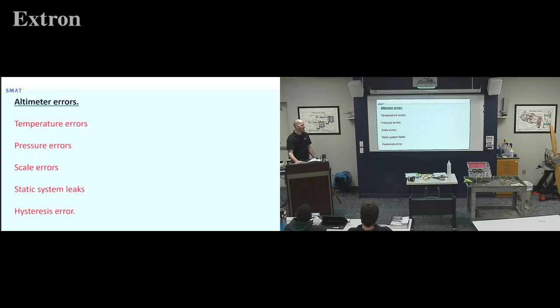Well, same kind of idea, hysteresis error with our altimeter is if you haven't been flying in a long time, the thing will get to where it likes being there, and then I go fly, it might not like being in the new position with the bellows, so an error because it doesn't like being, we call that hysteresis error.